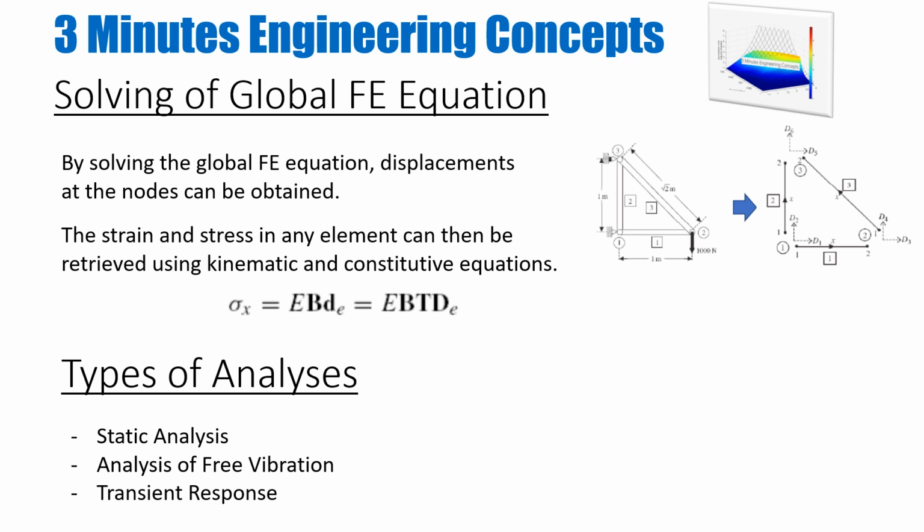So the idea of the whole exercise is you formulate these global FE equations, and then you solve them to find the unknown field variables. In this case, these are the displacements. Once we have found the displacements, we can use our constitutive equations and our kinematic equations to find out the values of strains and stresses in any element in the problem.